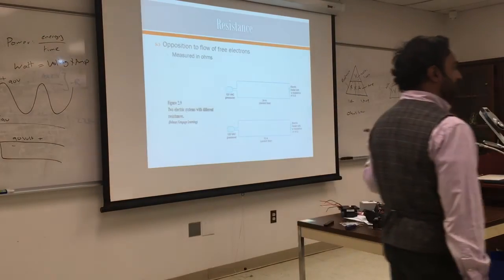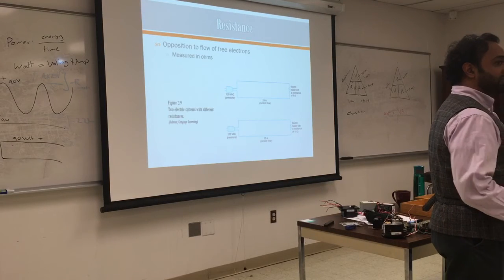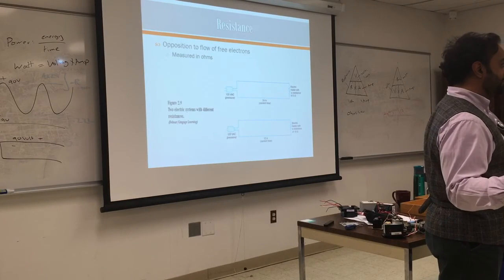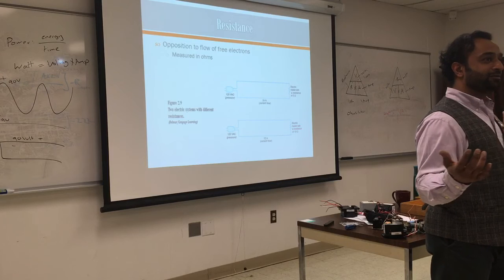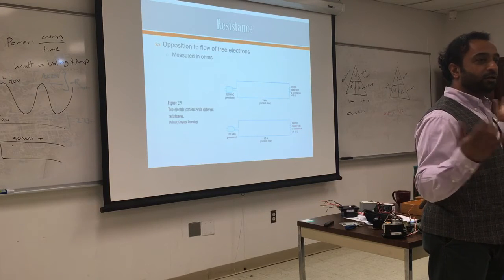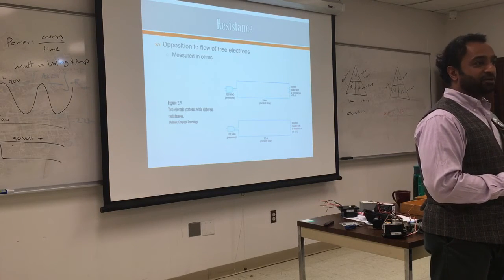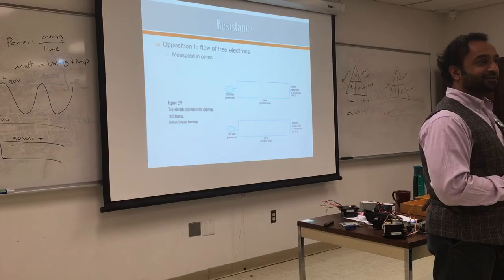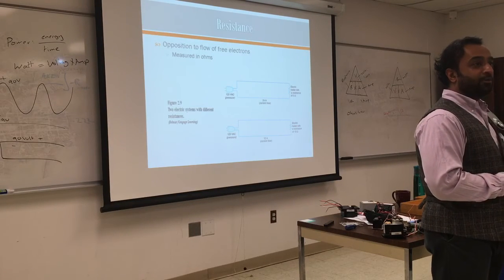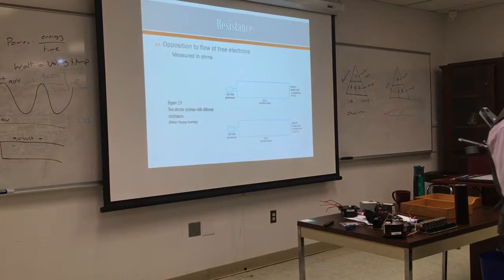Based on each piece of equipment, how much amperage they draw. What is the voltage in the house? You know the voltage already. What is the voltage of a household? 110, 119. You know the voltage, you know the amperage, so you know how much you're going to pay for that equipment. Now I think by law they put the wattage on every appliance. So this microwave is 1500 watts. That's 1.5 kilowatts. How much would that run me?